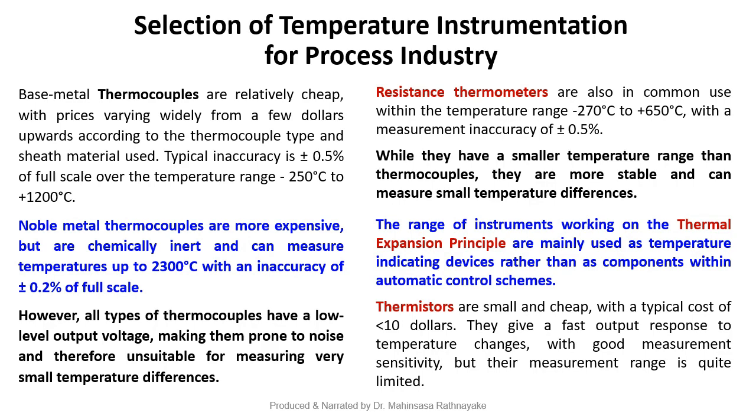Then the other thing is, sometimes thermocouples having noble metals are required because they are chemically inert, for corrosive environments and specific applications, where we would need to use these special types of thermocouples, which are a little expensive.